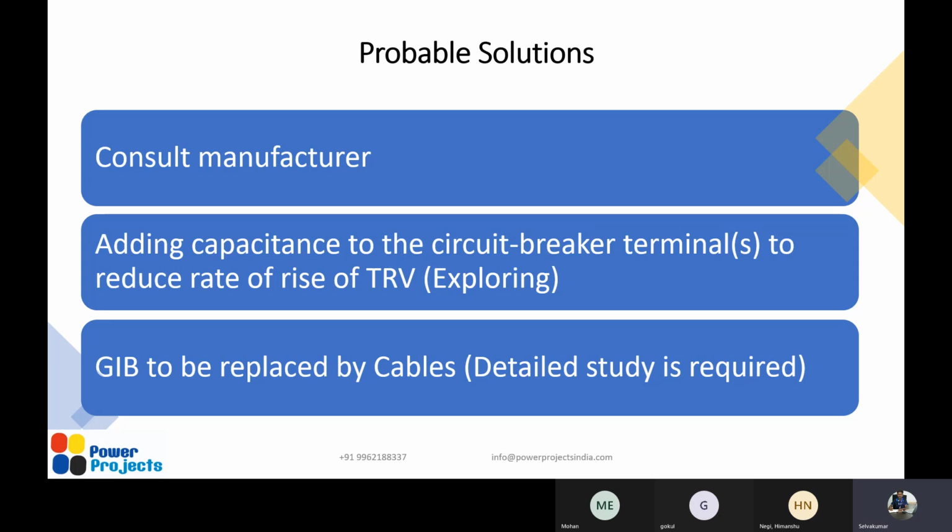So we thought it was only 1.3, and we had seen only 1.3 as the FPC, but now Gokul has asked how this TRV will increase if it's 1.5, correct? Yes. Then we know very clearly that this product is 1.5 FPC. So you need not compare with what is in the IEC table. You can get the right value from the manufacturer, and based on the FPC you can increase this TRV and compare that value with the actual value occurring.